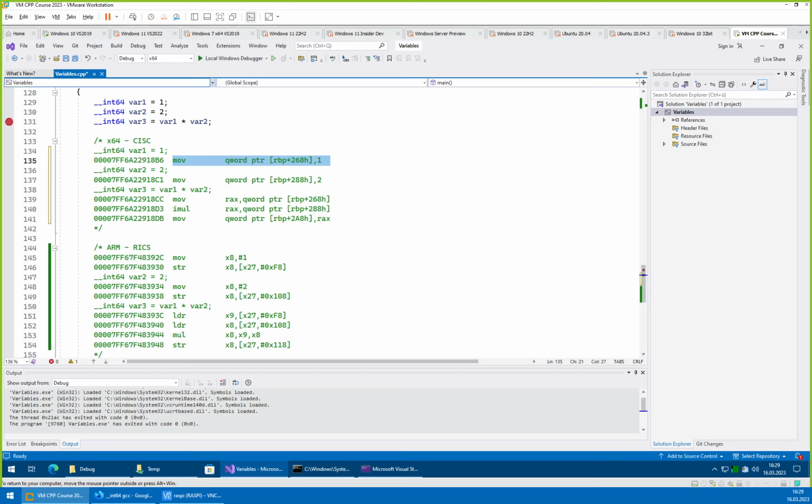But in many cases you will see that modern highly optimized complex instruction set CPUs are just as fast as ARM CPUs. The only thing where ARM CPUs are really, as it looks, hard to beat nowadays by the old Intel architecture based CPUs is efficiency in terms of instruction per watt, because the complex CPUs have to decode all the instructions. They have a lot more overhead, and while they can kind of gain speed by throwing more and